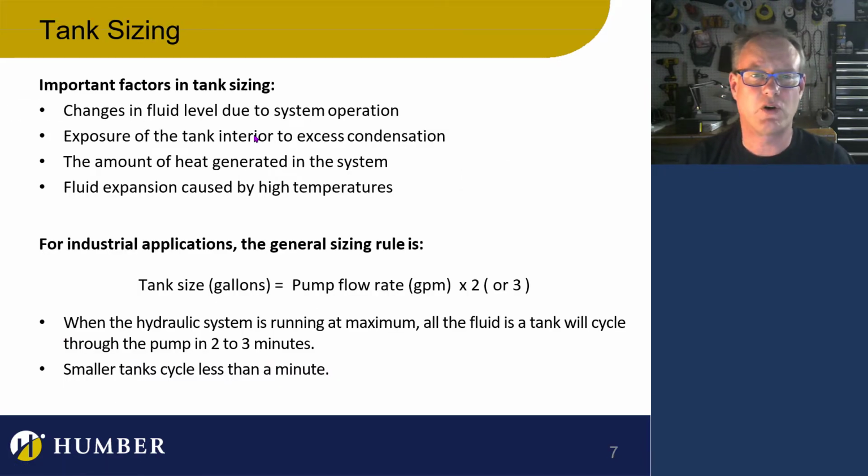Tank sizing. Important factors in tank sizing: you have to be able to change the fluid level due to system operation. As the system is being used, the fluid is going to go into a cylinder. Say you have 3 or 4 cylinders and they're all extended. All of that fluid is now going to be in those cylinders.